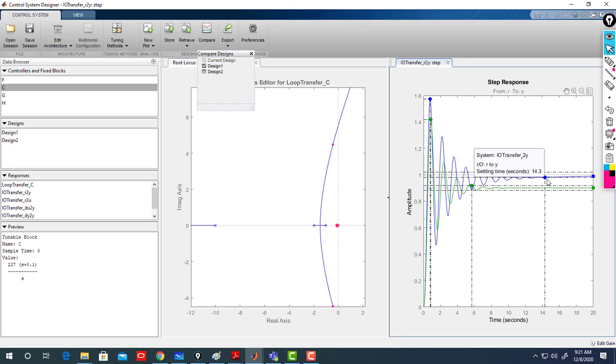Well, settling time is more for when it reaches a steady state. So this is affected, of course. It makes sense that the system becomes slower when you add an integrator. System becomes slower in the sense it settles slower. But in terms of rise time, overshoot, peak time, still the same. So that's how we answer the question. That's how we show it.